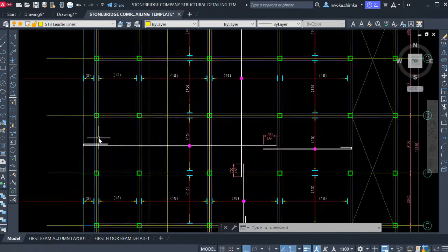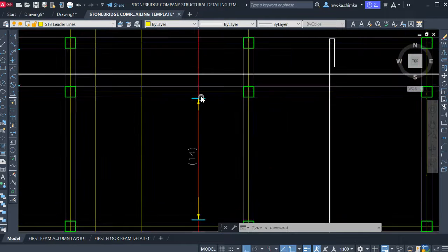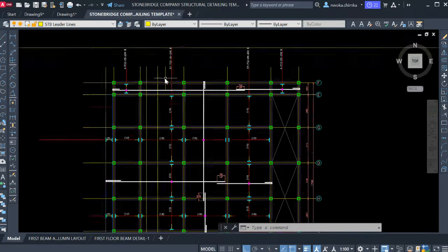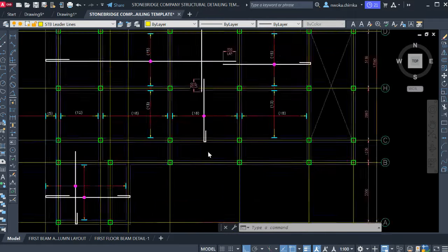This reinforcement, which is here, you can see it here, this bottom reinforcement runs from this point to this point and stops. Now this other reinforcement, because of its shape, picks it up from this same point and finishes it over there. So the same thing happens. We now have to also detail. We have also done it for this one.